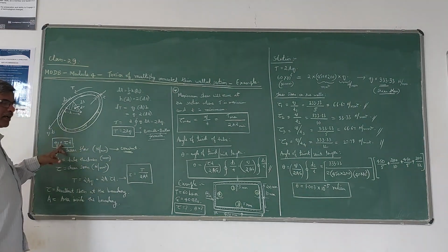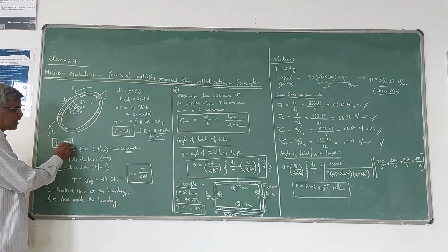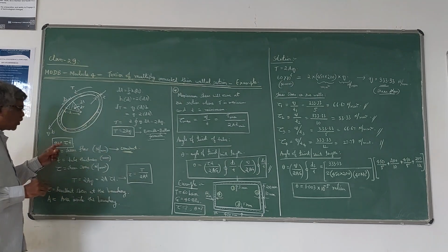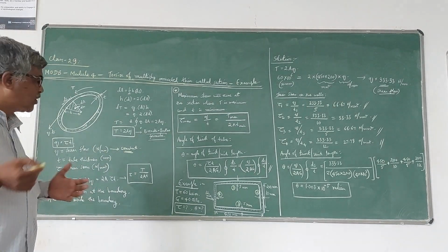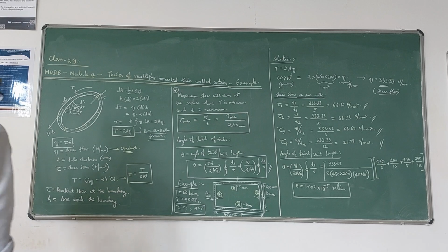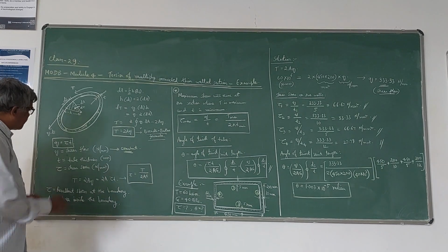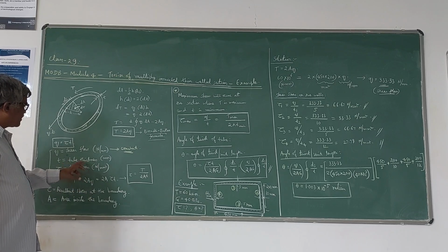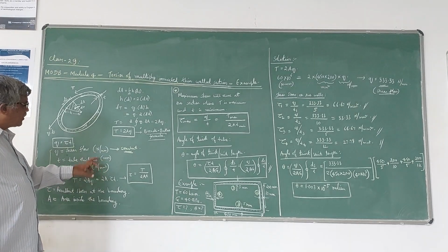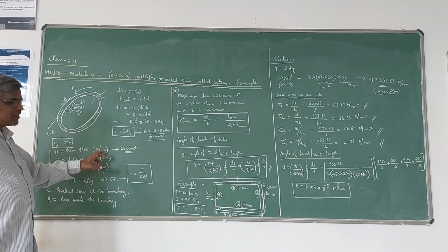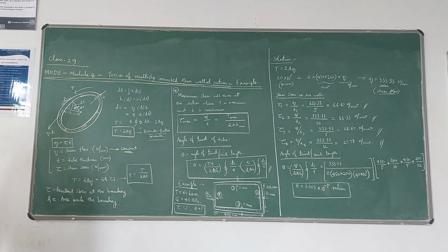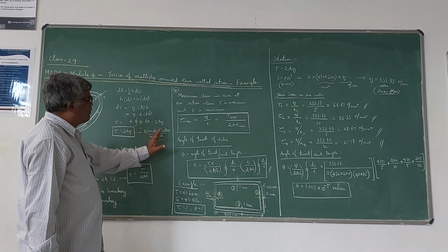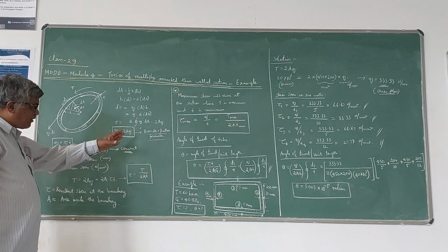That q is obtained by multiplying the shear stress by the thickness of the tube. So actually this q is a constant. That means tau and t may vary, but q won't vary. It is a constant. Here you can see the units. Tau is expressed in Newton per mm square, thickness is expressed in millimeter. When you multiply, you get Newton per millimeter, which is a constant. This is according to the theory developed with the Bredt-Batho formula.